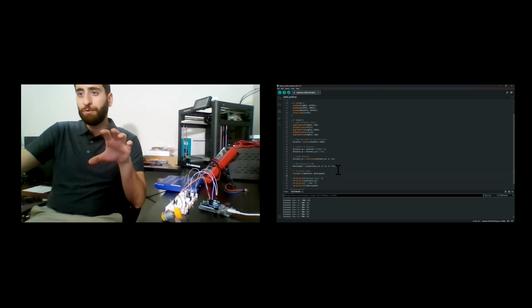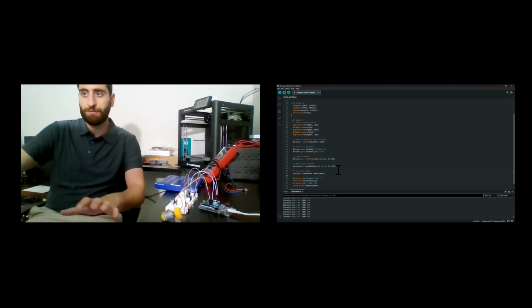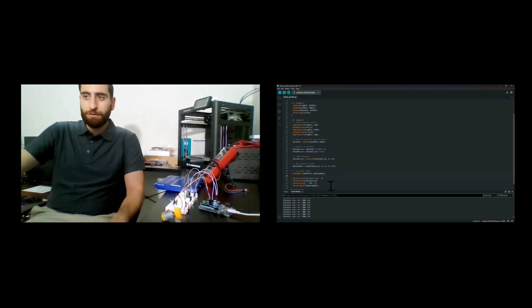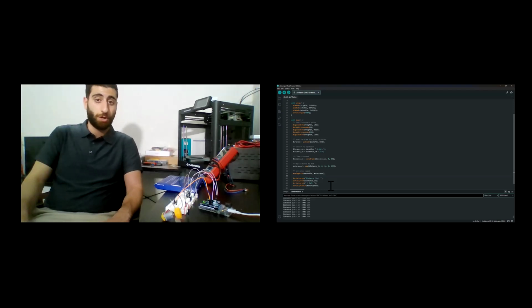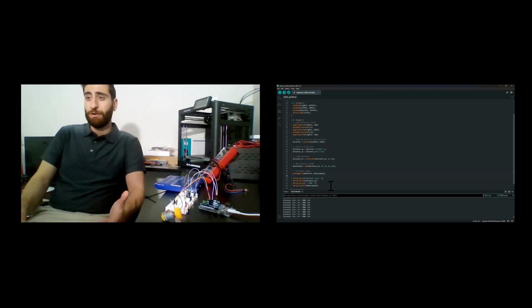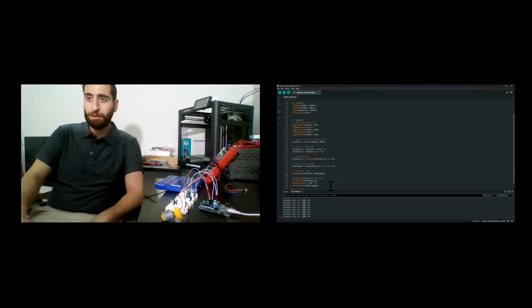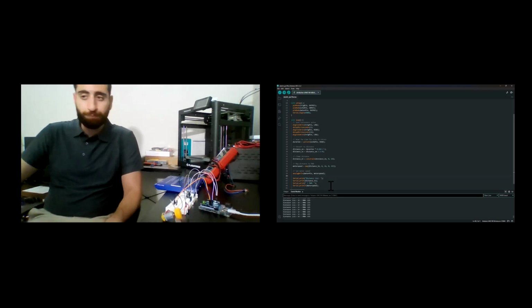And then from that, we're able to map the distance from 0 to 16 inches here in this case. We clamped it at 16 inches just to constrain for the sake of this example, from 0 to 16 inches to 0 to 255. So 255 corresponds to 100% duty cycle. However, 0 corresponds to 0% duty cycle. So if distance was 0, it would stop the motor from spinning as it is stopping the vehicle.